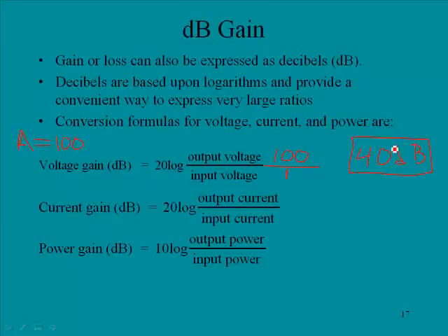Now, keep in mind that when we use the term decibel, this is a unitless value, and by that I mean this simply represents the relationship between input and output. Since we had 1 volt of input, 100 volts of output, we're taking 20 times the log of 100.